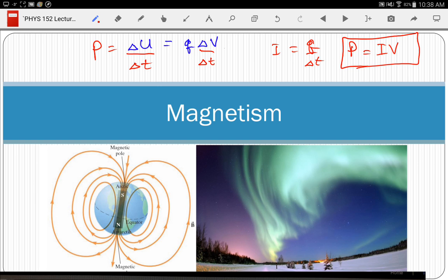If you have a resistive material, you can use Ohm's law to say power is equal to I times V, and since V equals IR, that's I squared R. Or you can say I is V over R, so it's equal to V squared over R. So for a resistor, those two are also equivalent. But don't get confused and try to use those two on a power supply, because the power supply doesn't have a resistance there. That's only true if you have Ohm's law available. So for a resistor, that's how you calculate the power.